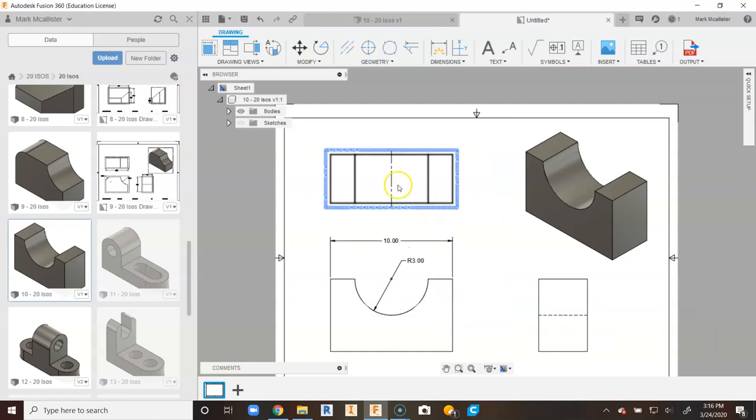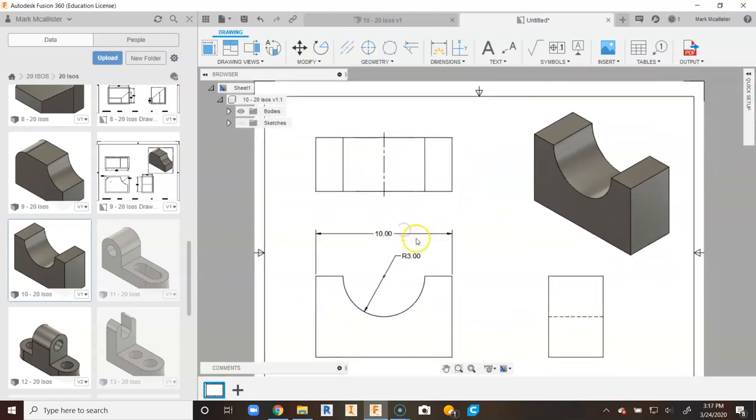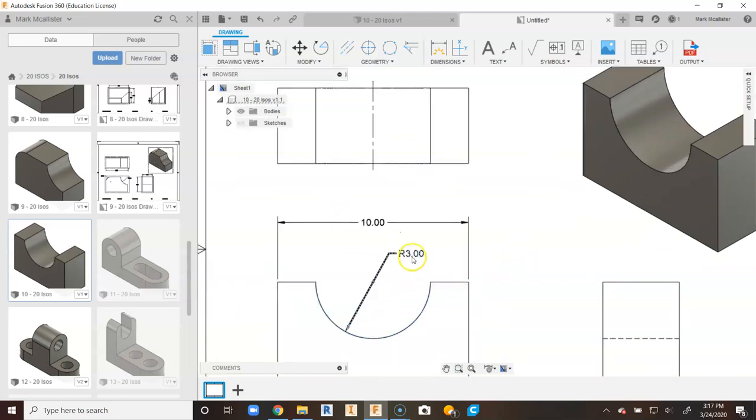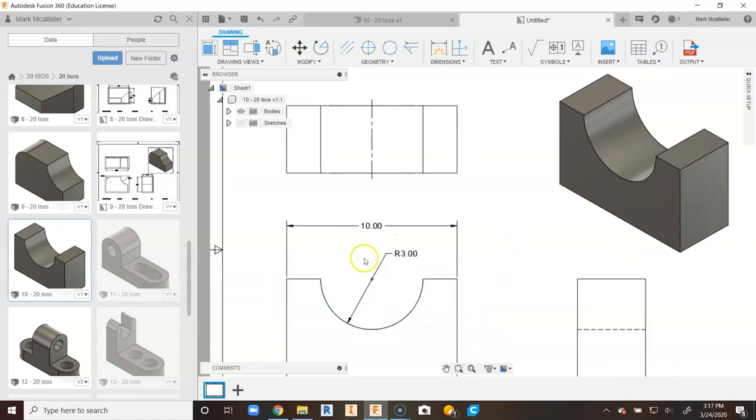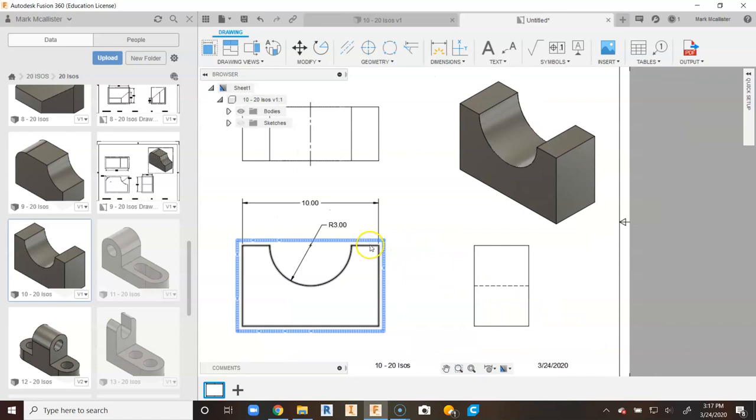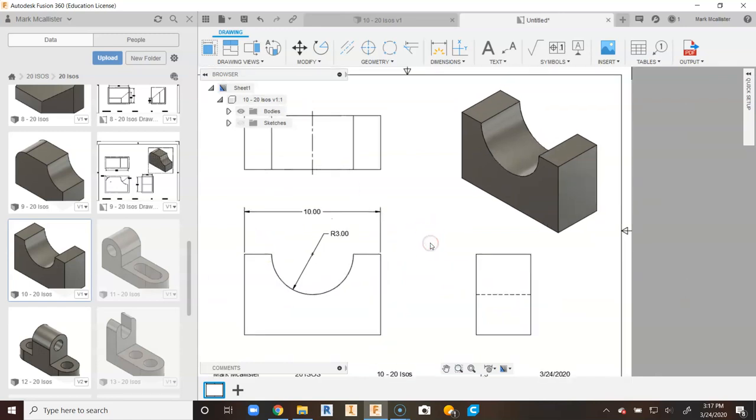We've said that this is a symmetrical object by the center line, so what we can do is just say, 10 minus 3 is 7, divided by 2... should be, it'll be 6 because this is 3 times 2 would be 6. So 6 from 10 is 4, so each of these over here on this side should be 2. That would be what we would call an inferred dimension. So again, I did what a common mistake sometimes students in my class will do, is they'll just go ahead and not multiply this by 2. The distance from here to here is 6. So each one of these would be 2. We do not have to place that 2 dimension on both of these sides because it is a symmetrical object.